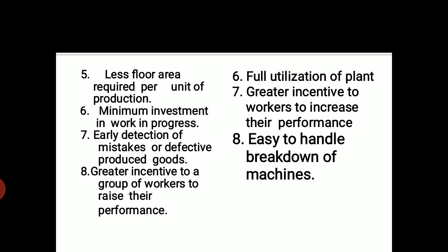In the rest of the layouts, the product moves from one machine to another one and to the next, and likewise. But when we are talking about the static layout, what is its speciality? The product does not move. Instead, whatever the services, the people, the material, the machines, the equipment, the facilities, whatever you require, it moves around that particular product, right? And that is why it is known as fixed position layout, or it may also be known as static layout.